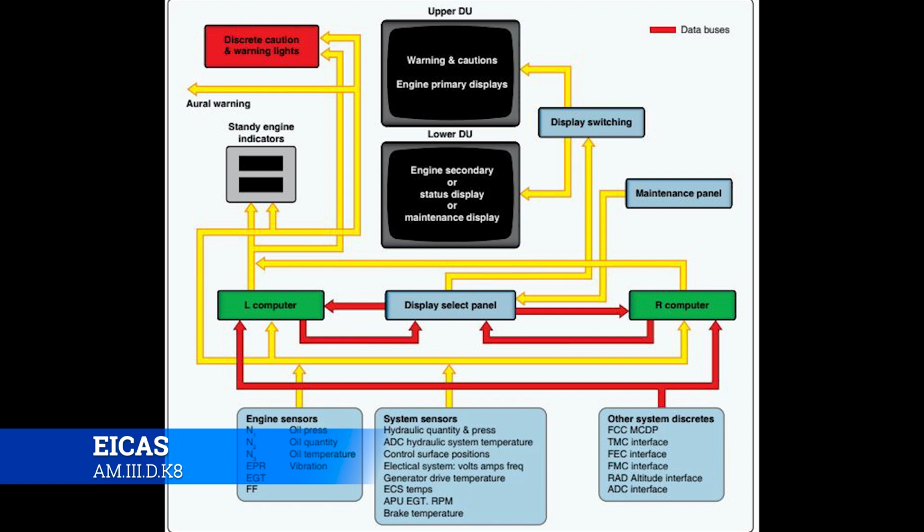So system sensors, engine sensors, it gives that raw data that goes up to the computer to be signal conditioned and then pushed over to the display. And then also all your other systems, FEC, FMC, RAD, ADC, all those kinds of airframe-like systems can also be fed into there as well as all the sensors like we had said. There's also going to be an opportunity for standby engine indicators to be tied into it as well.